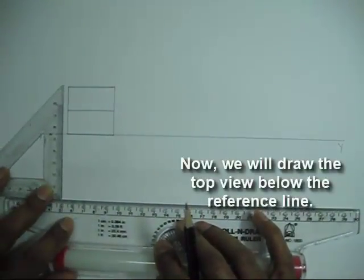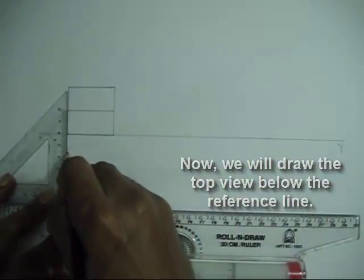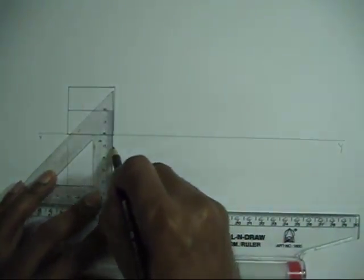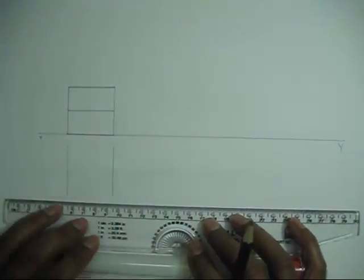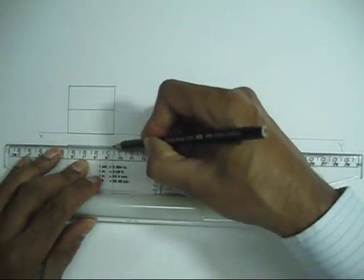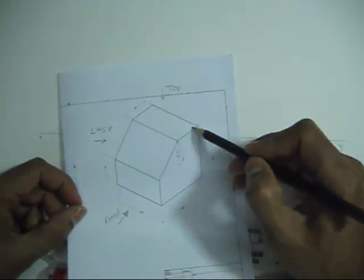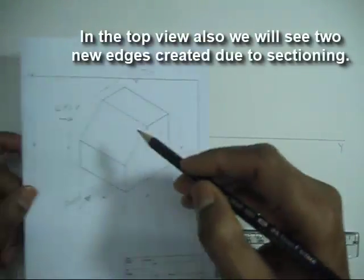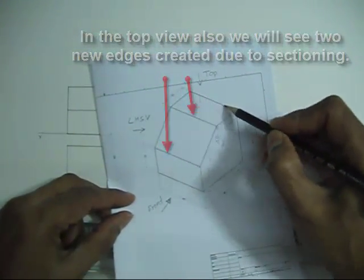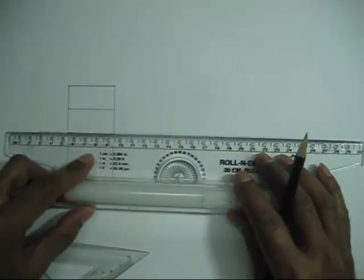So now we will draw the top view below the reference line. So these are the outer edges of the top view. So in the top view we will see a rectangle, this part, and the inclined part will be projected. So the inclined part will not be true length but rather projected dimension.